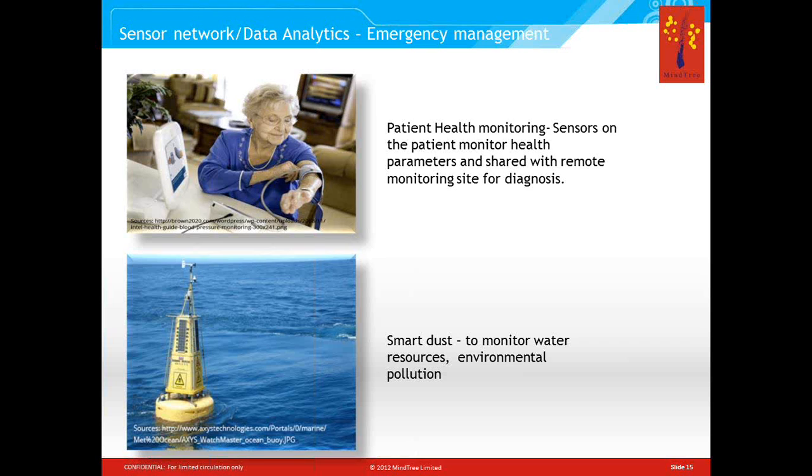And one of the features of such wireless sensors is power. Many of these sensors will take power from, say, solar or their environment, wherever they are, like scavenging, energy scavenging or energy harvesting, as they say. If there is vibration available, they will use the vibration to generate energy. If solar is available, they will use solar or thermal energy to generate the power that they need.